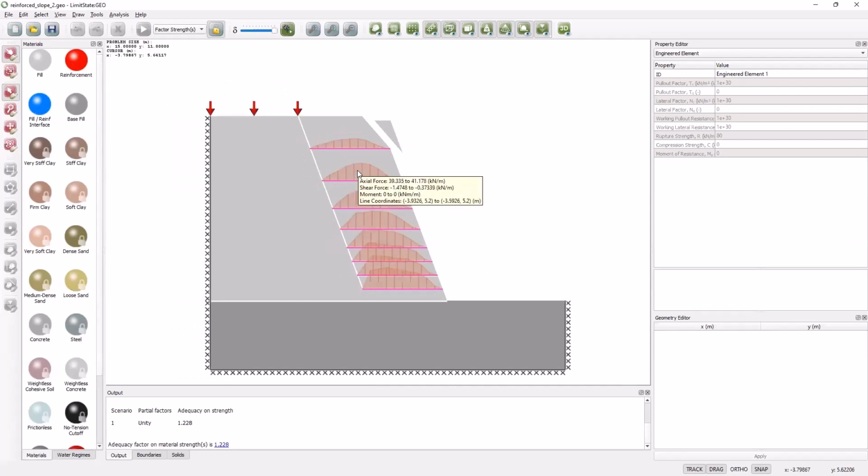And if that tensile force or axial force equals the tensile strength of the reinforcement, then that will be the point at which it is failing. So you can look at it in two ways: in the animation, if the element is stretching, but also you can look at these graphs of forces and check to see whether they've reached the failure load.